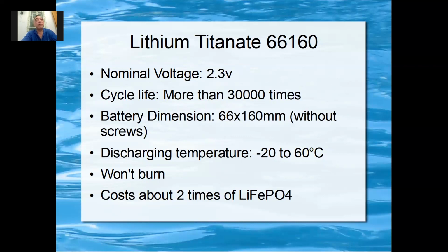If you use your phone until it's flat, and then you charge until 100%, then you discharge fully, and then charge again, then you won't get 1,000 cycle. Or even if they put 5,000 cycle, you won't get it. So you get much less. So the number of cycle doesn't mean that you can discharge fully. It's only 20%. But for lithium titanium, it's not an issue.